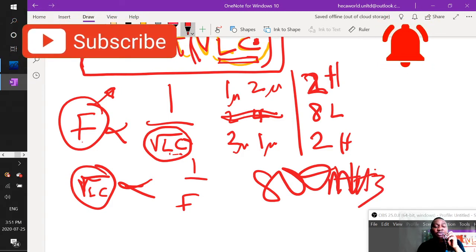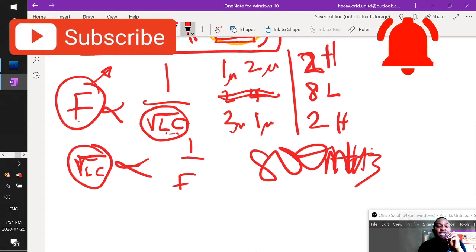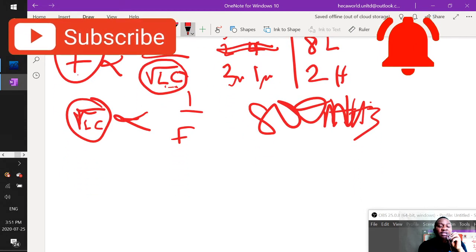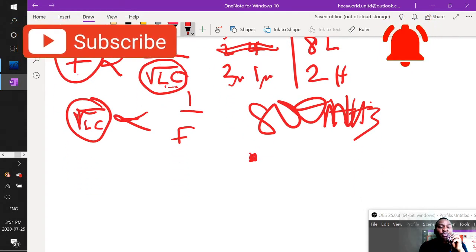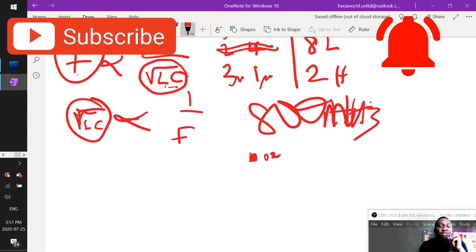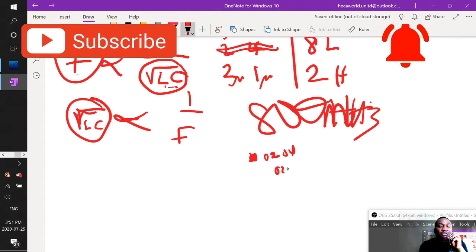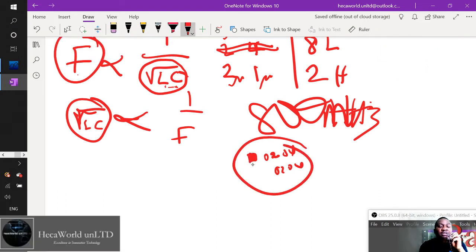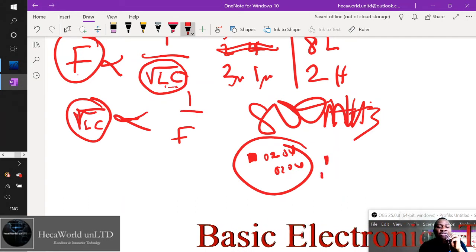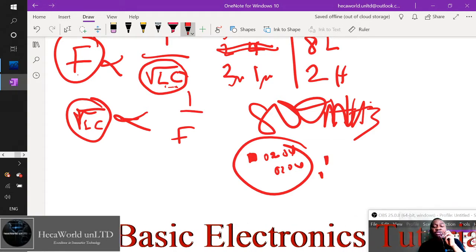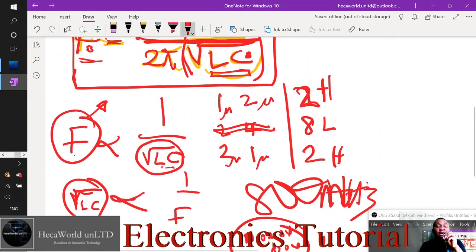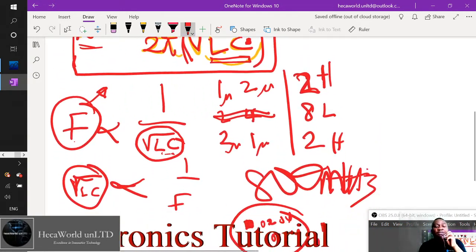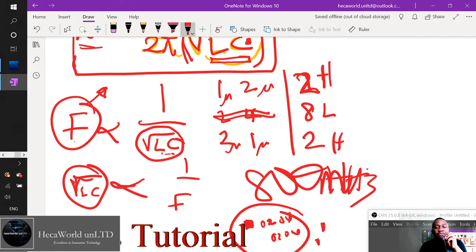And if you want to go to gigahertz, sometimes you don't even have physical inductors. You just have small components, 0202, 0204, very small components functioning as capacitors and inductors. Sometimes a straight wire, depending on how high the frequency is. Just a very short wire, microstrip, is all you need to make an inductor, depending on how high the frequency you want to make, right?